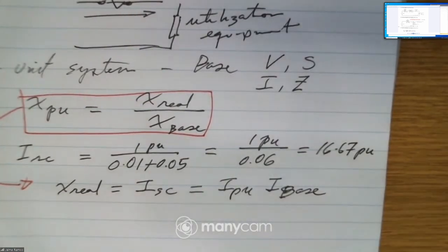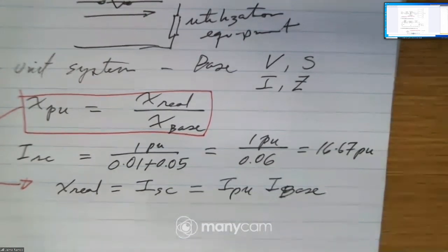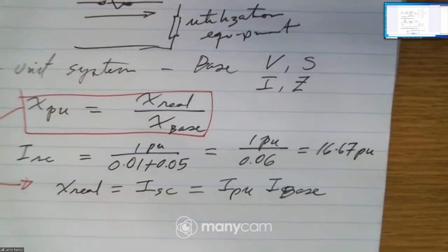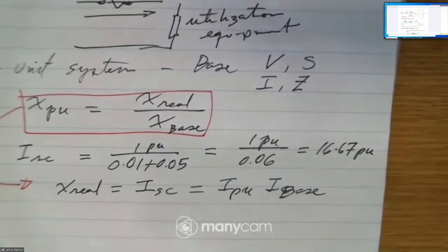So that's the short circuit current, 23,100 amps. Very nice. So here the very interesting point is that the transformer is represented in the per unit system by its impedance. So that's quite a fact, isn't it? That's quite a fact. So how can we do that?